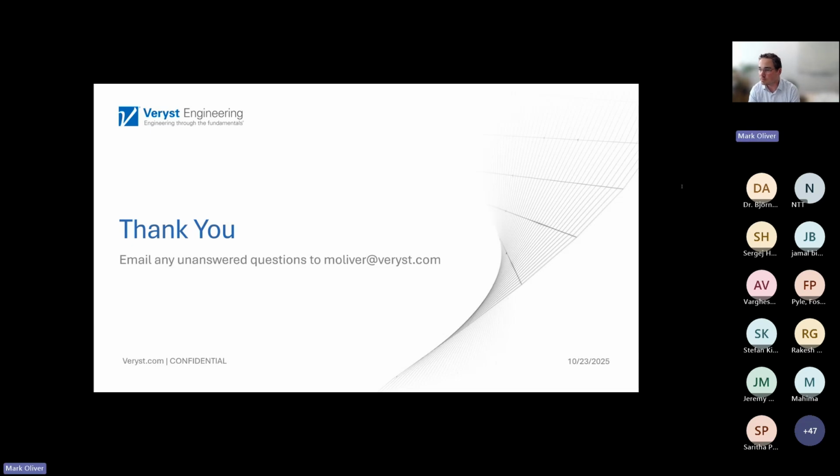Okay, the question here is about special mesh requirements for cohesive elements. We didn't get into the numerics, and this is a big topic, but some general thoughts. Cohesive zone modeling works best when your fracture process zone is engaging at least 3 or 4 elements.